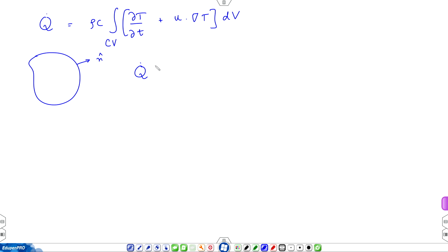In the handbook approach, how did we specify Q? In the form of losses taking place in the tubes. Okay. So, in the global analysis, Q is prescribed from handbook information. In local analysis, what do we do? We have to introduce a material function. That is very similar to the stress strain rate relationship we had introduced for the momentum equation.